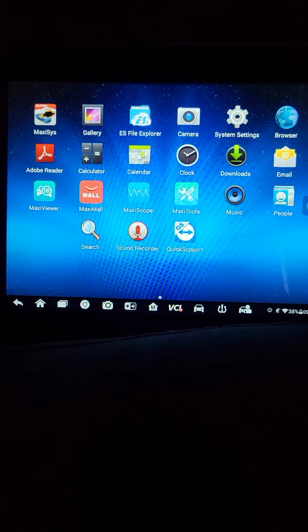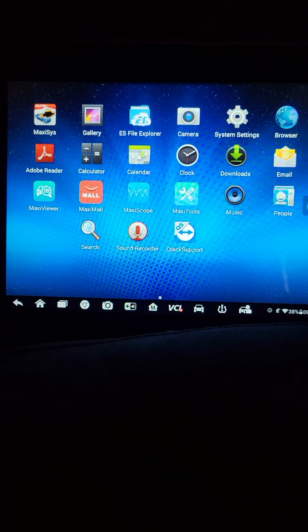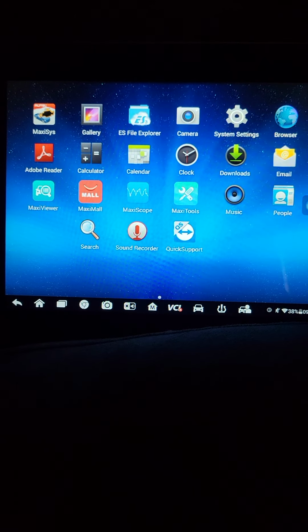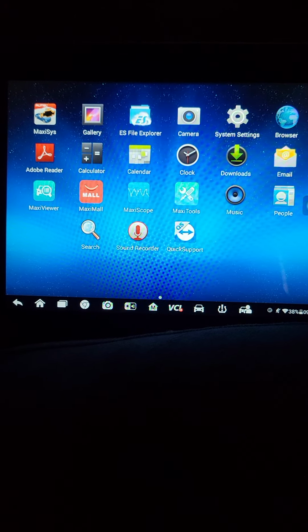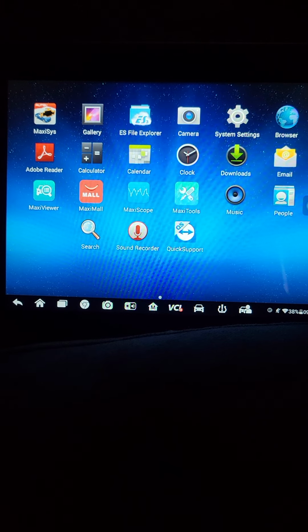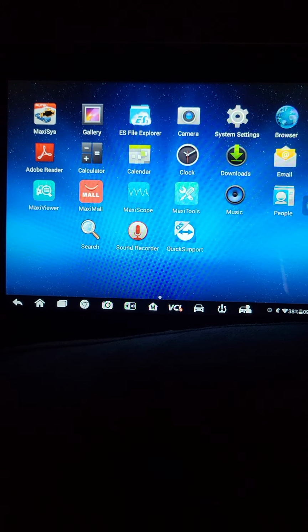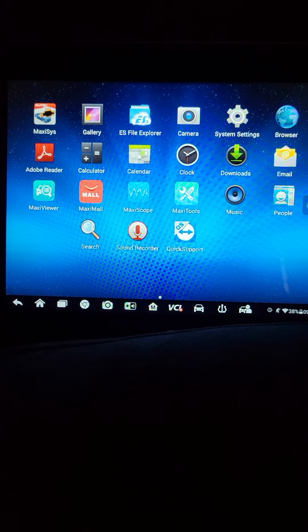Or they'll electrical tape a sensor plug to the top of the sensor, and then that tape melts because of heat and comes loose, and then that plug comes loose, and then you're screwed again, pardon my language. But that's what's happening.